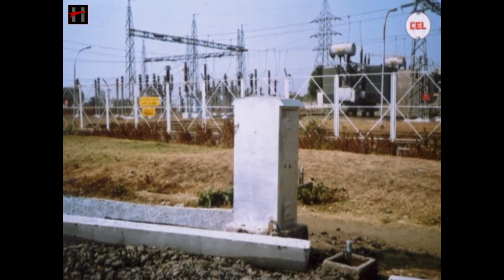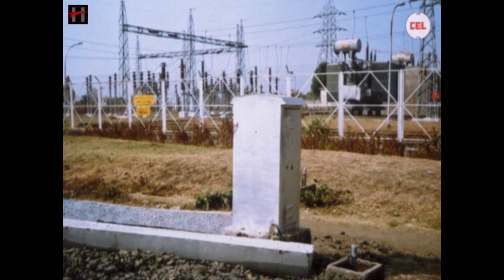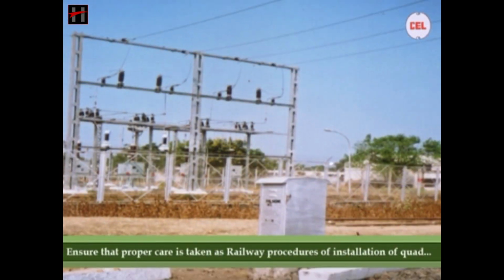While selecting the site for axle detectors near high voltage SSPs and feeder stations, ensure that proper care is taken as per railway procedures of installation of quad cables and proper earthing arrangement.